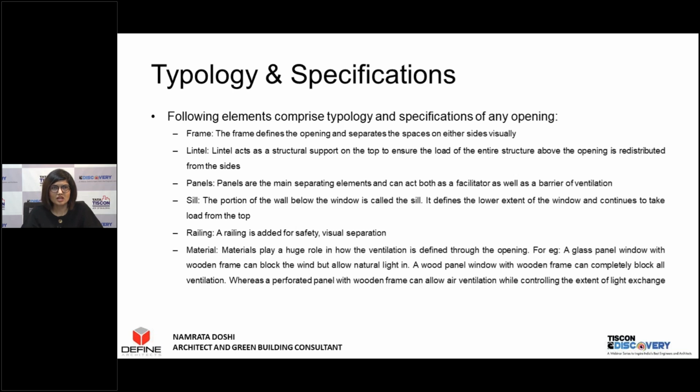If you're going to have, from a vision point of view, for example, a large door, you can choose to have one panel or more panels of glass within the wooden door or within the metal door, so that adds to your vision. So choosing the right material to contribute to your ventilation design becomes very important. So again, just to quickly summarize: frame, lintel, panels, sill, railing, and material. These are the factors you need to remember when you are designing the openings for buildings.